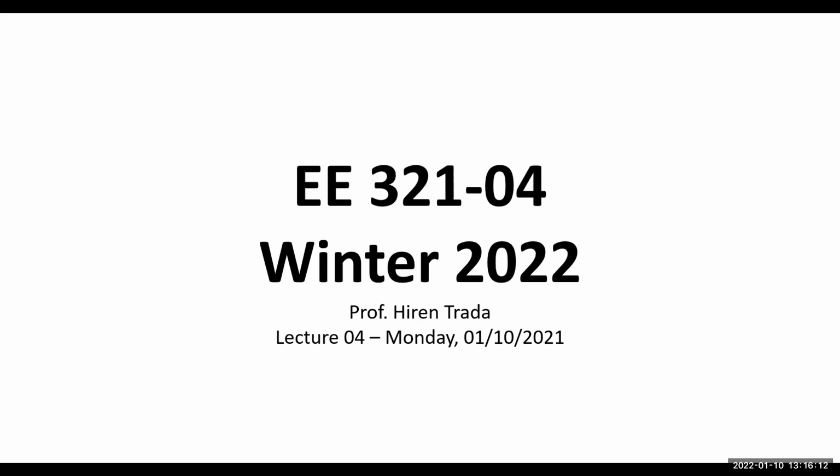Then there's a reverse breakdown region, shown with fire over there, meaning the diode could be damaged. In real life, we do have diodes that are specifically designed to work in this region. It is also known as the Zener breakdown voltage, VZ. And again, we'll look at Zener diodes later. That is the diode that is specifically operated in the reverse bias region. Okay, so the technique I wanted to talk about today is known as load line analysis.